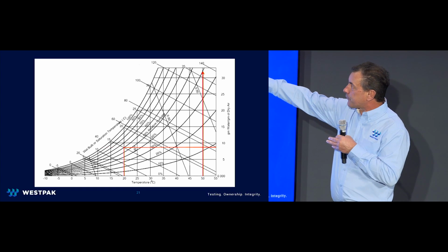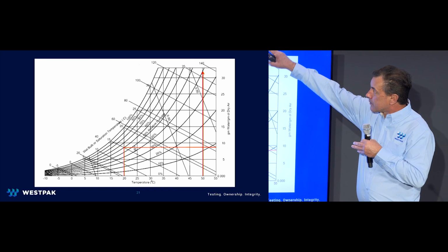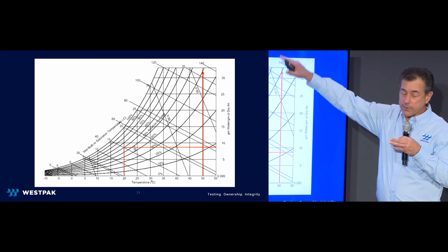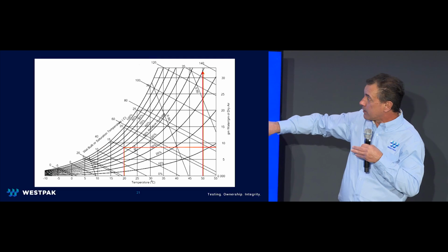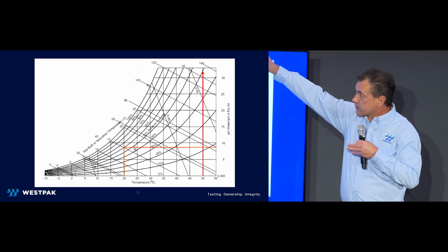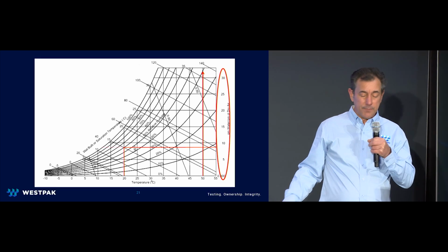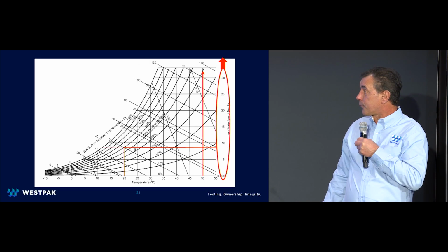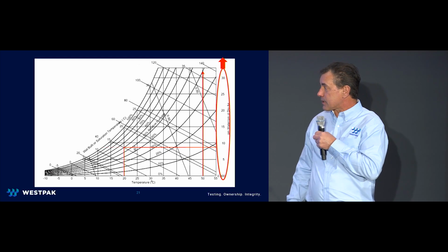We don't even get to 45%, which is the minimum. So really, we're talking about adding enough moisture. This is how we add moisture into the air, by adding steam. It's off the chart. So are we going to use plus 50 C and 45% relative humidity? 50, 55%?